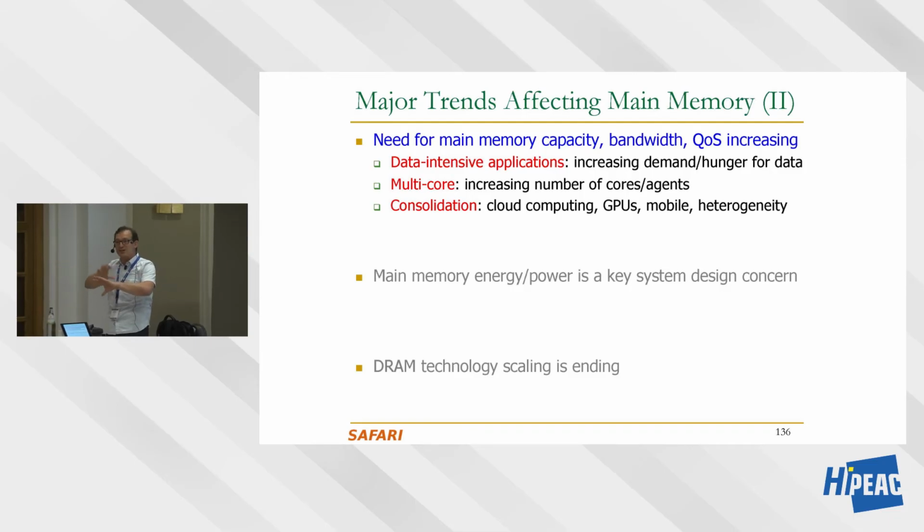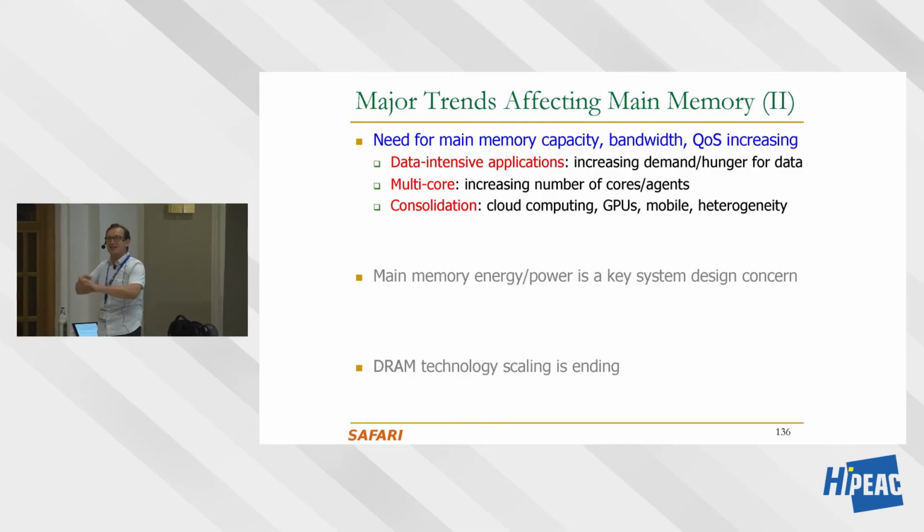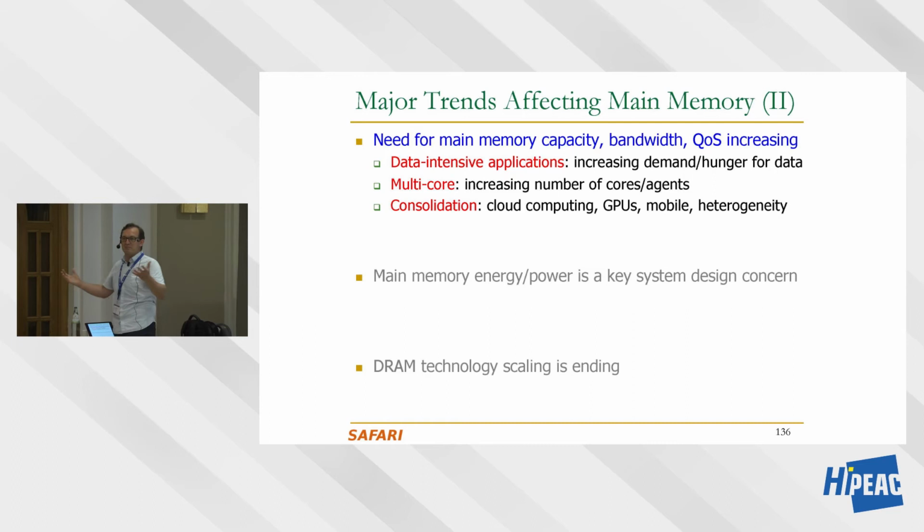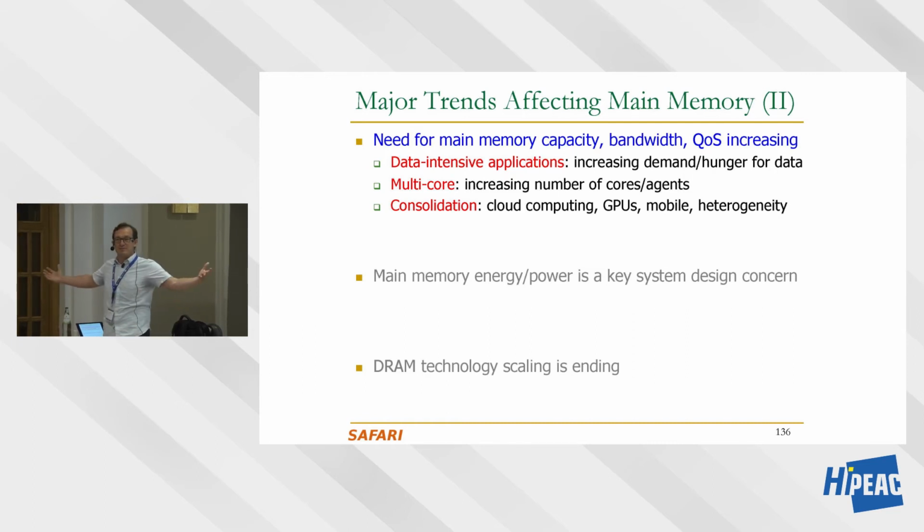You really need to orchestrate the data, and most of your chip eventually becomes caching, buffering, large amounts of caching, interconnect. There's no reason why we cannot put lots of cores onto a chip and no memory at all. But it doesn't work that way, unfortunately, because we cannot supply the data to feed that large chip.